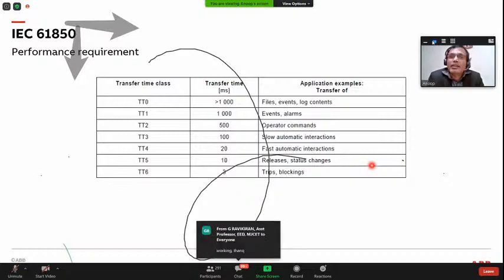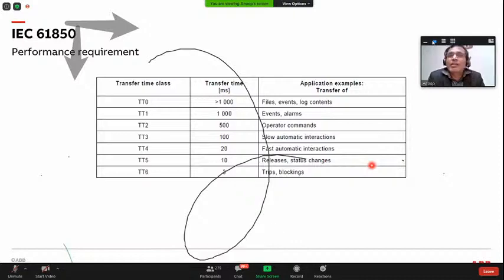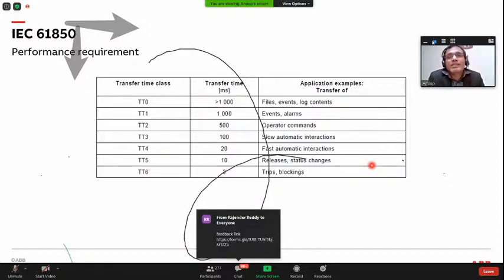So it makes sure that your function doesn't see it as a fault condition, because during charging of a power transformer, from the no load current, it might take around 25 times, or it depends on the waveform where you are switching that specific transformer. It will take a very heavy current. So looking at the harmonics, it will decide whether it is a fault condition or an inrush condition.